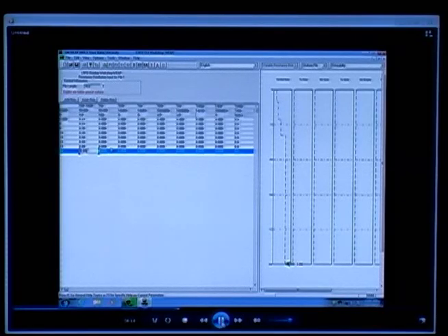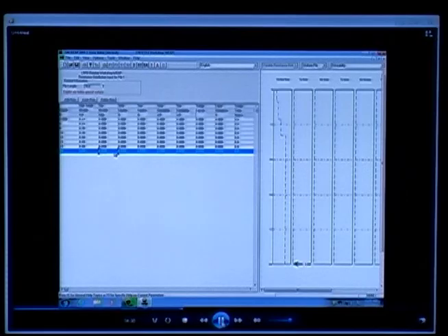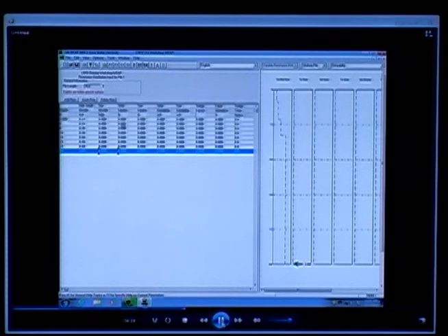Since the SPT N value of 12 at the fourth layer near and below the pile toe is too small, no toe resistance is considered here. The other parameters such as the quake and damping will be considered later.